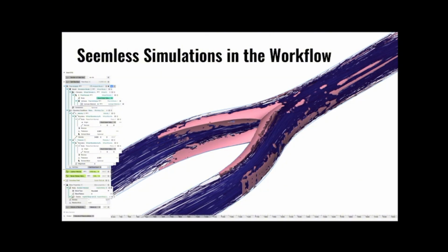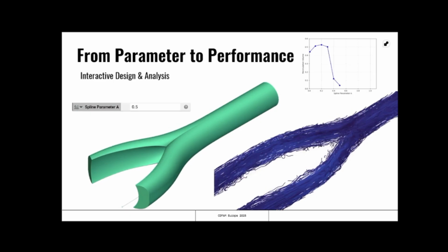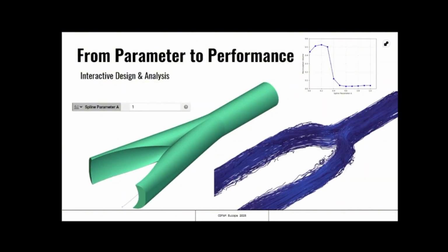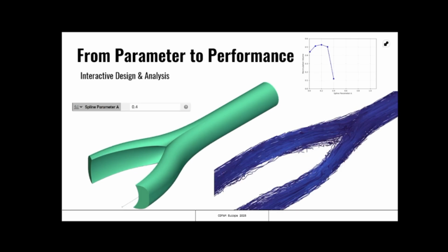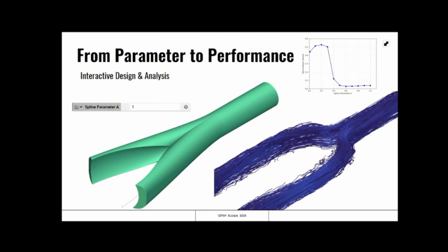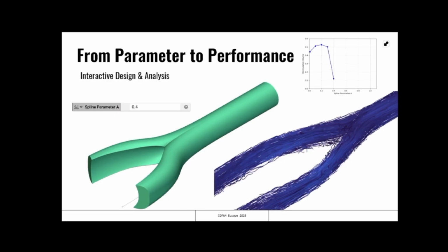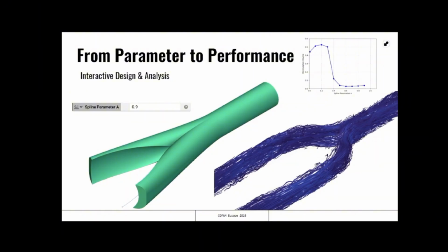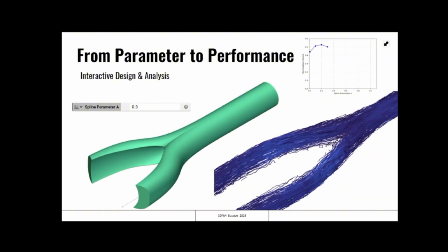Because this is robust and it runs fast, you can very easily set up a DOE or an optimization workflow for that. Just to give you an idea, running this with 400,000 voxels takes about 10 seconds on a laptop GPU. Running it with 4 million voxels takes about 5 minutes. So this whole series here is set up and executed in about an hour. And this allows pretty much to iterate through CFD performance early and pretty much before validation in preliminary designs.